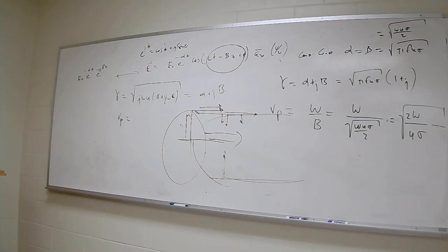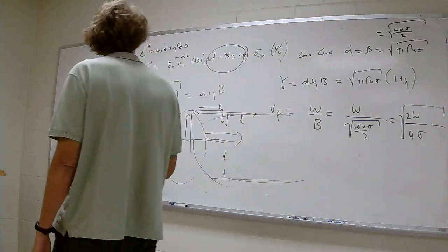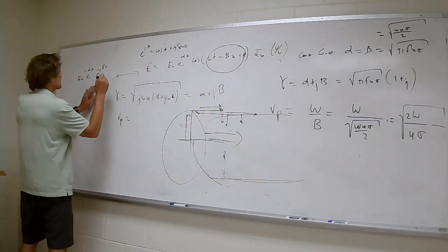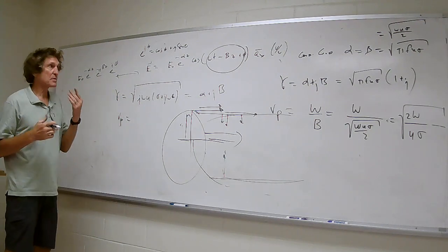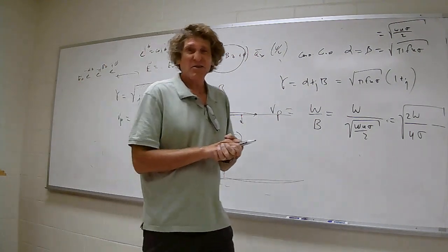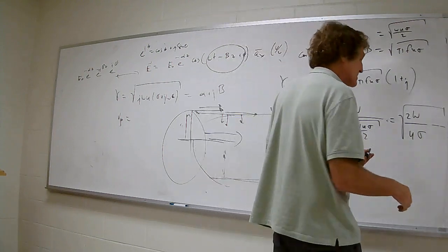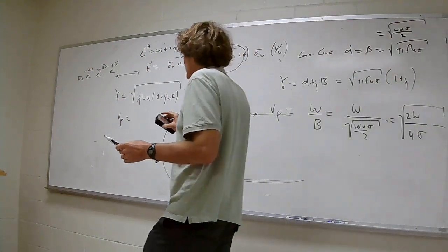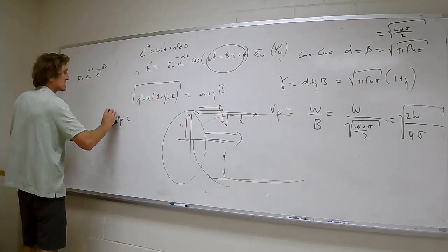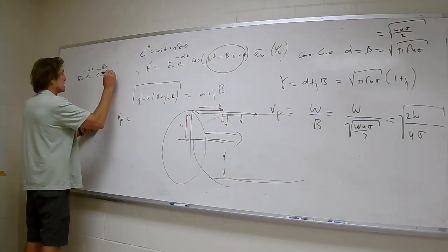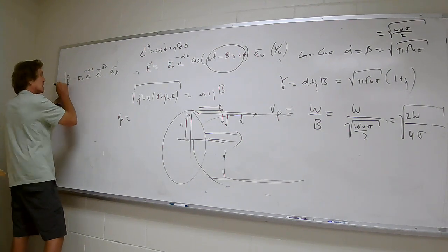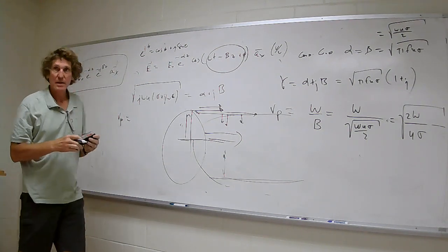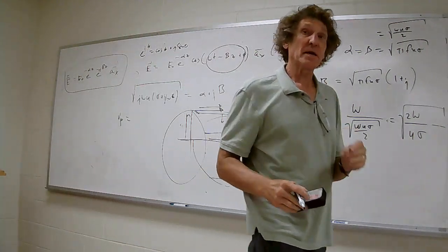What about your phasing? If there's a phase angle, then it goes right here. Think about that. That's a plus, right? So it'd be e to the plus j phi 1. With me? But that's an implicit phase angle there, and usually it's zero. I'm going to make it zero just to let you appreciate what I'm trying to tell you. So if this is the case and it's a_x, this would be the phasor form of E, right? Y'all with me? Yes. If that's the phasor form of E, it's a propagating wave, isn't it?